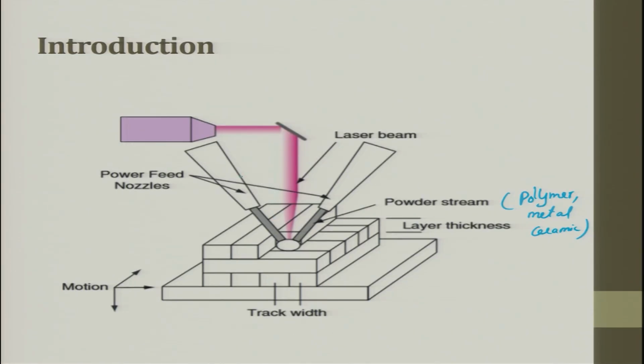So, it is very clear. You can see here you can have multiple nozzles feeding the powder, and then you have a laser in the center which exactly focuses it and then melts it. So, you will have an optic system in between. In the schematic diagram we do not show it, and this is called a galvo stage, which swings and sweeps to get the XY plane data.